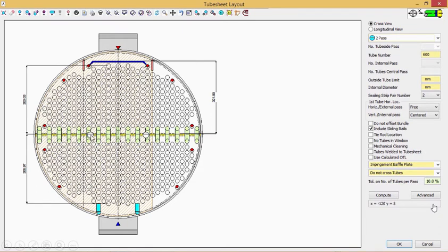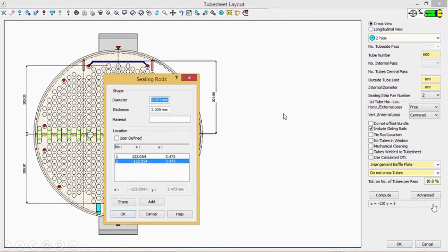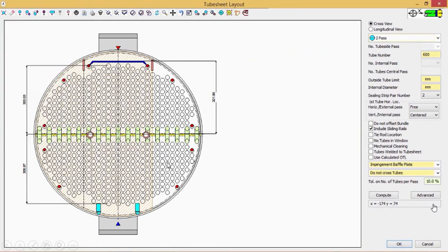Now we can change the ceiling rod dimensions similarly by double clicking and then modifying the diameter, etc. You can erase tubes along a segment or along a line. So for instance, if I want to erase the tubes along this line, I can do very easily by clicking on that option. You can undo it very easily. You can erase tubes within a rectangle. Hold your button and then release it where you want to end the opposite vertex of the rectangle.